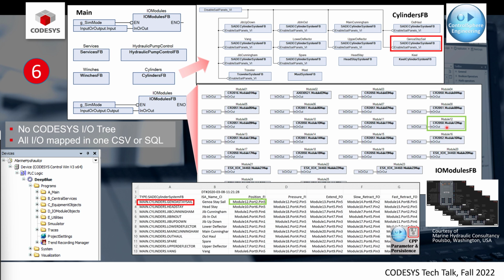So just place your equipment objects, both your traditional plant equipment and your IO modules. Configure your equipment, including the IO mapping for each piece of equipment. Place and link your IO visualizations, and you're done. No adding variables to the global variable list, no copying programs or visualizations, no modifying programs to global variables, no mapping new variables to new visualizations, no adding items to the unit conversion list or the persistent list or the log list, no mapping individual tags to the IO, and no adding items to the alarm manager.